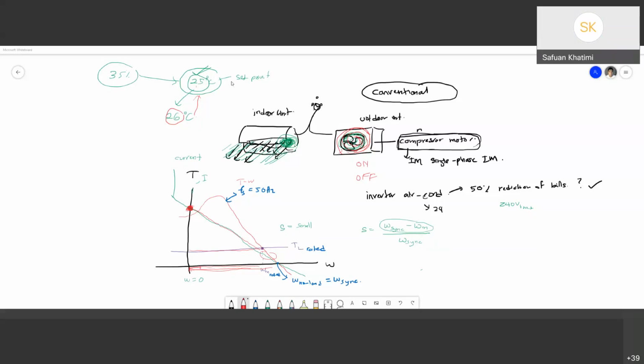It saves more energy. Save current. Yes, to save the energy current. Because when you see here, when it reaches the set point, the speed will actually reduce. For example, maybe at this point, you can see that when the speed is at this point, the current is high. This is the current. So, rather than keeping the motor always on, why don't we shut it down? If you have set the point here and you keep it always turned on, the current is actually operating at here. Okay?